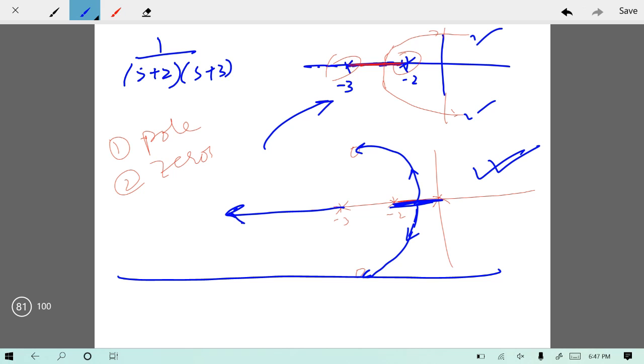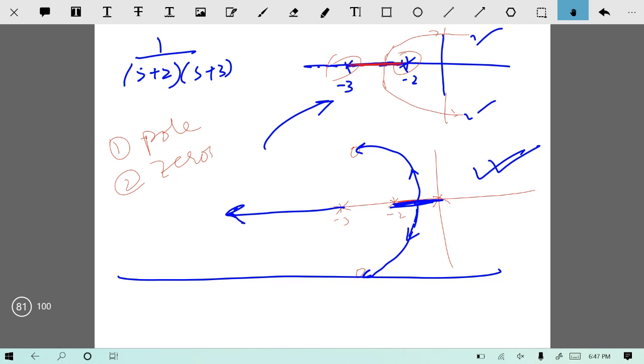In the older root locus without PID controller, the system had the tendency that your two poles are going to infinity on the path of asymptotes. However, when you added a PID controller, two poles got their zeros and their root locus terminated in the left half plane, and instead of going towards infinity they just terminated in the left half plane, and the possibility of system becoming unstable becomes absolutely zero. So this system can never become unstable.